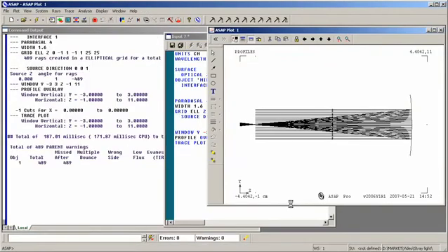We execute the file. We find that we don't see much difference here. It looks exactly as it did before because we're tracing only the base rays graphically, but in fact ASAP is also tracing the parabasal rays in the background. To find out, we can do a wave optics calculation.